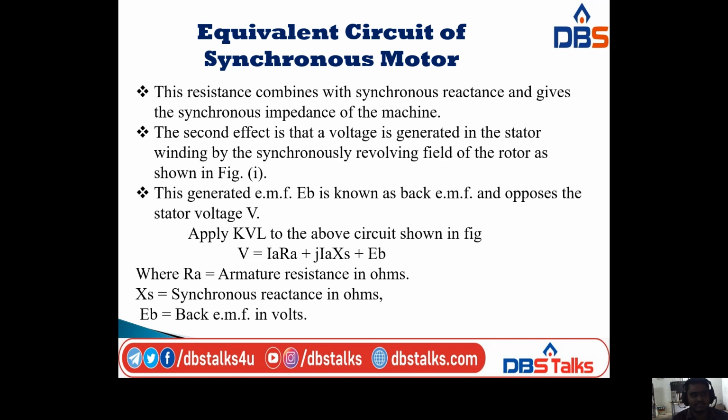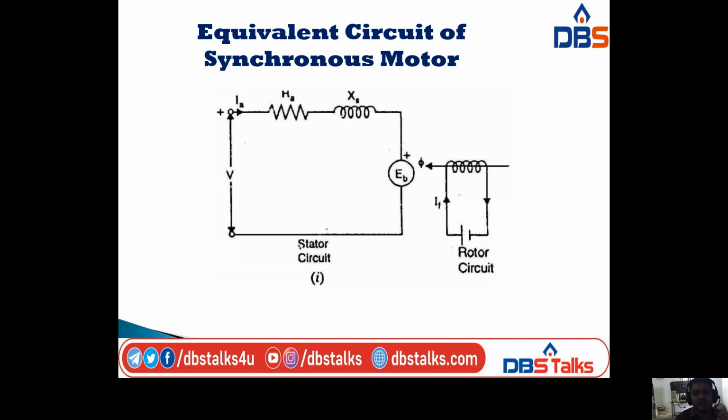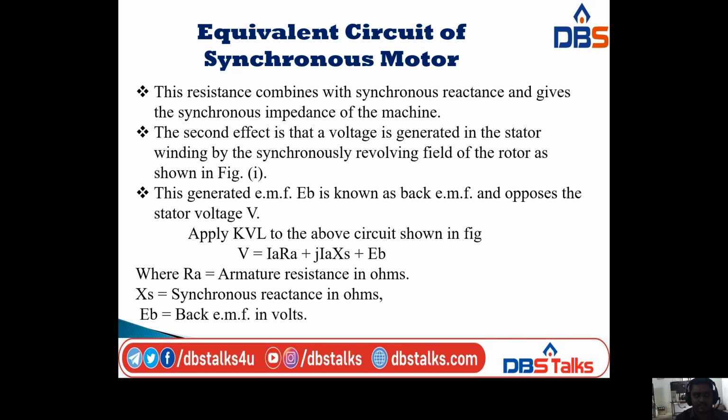This generated EMF, Eb, is known as the back EMF and opposes the stator voltage V. Here I am applying KVL to this circuit. After applying Kirchhoff's voltage law, we have the equation V is equal to Ia Ra plus j Ia Xs plus Eb.